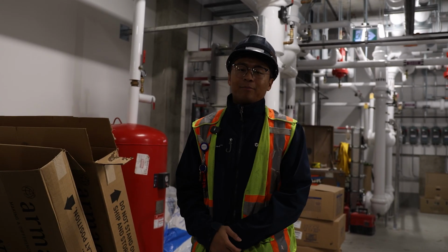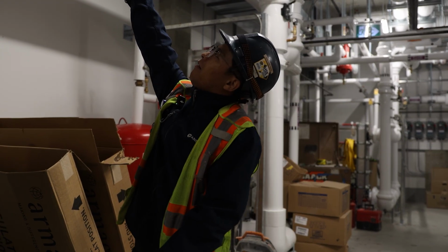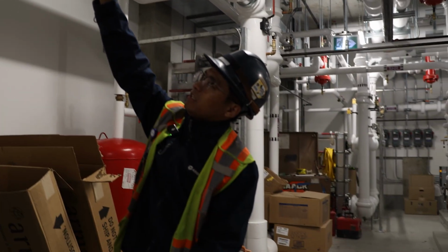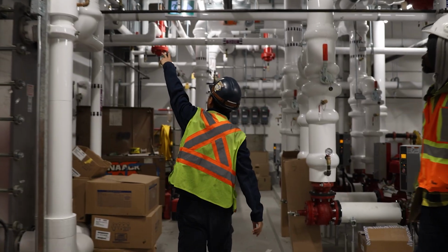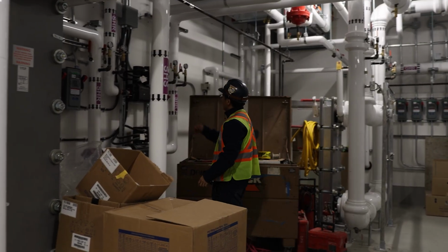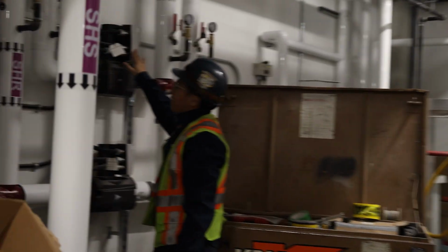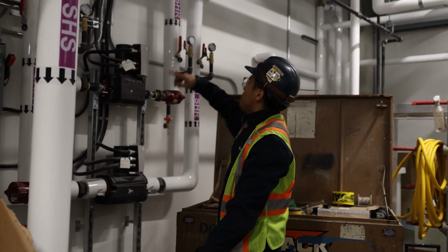Okay. Hello everyone, welcome to the solar section, domestic hot water solar. And those 2 are the pipes from the solar. One goes return to the solar, the other one is the supply from the solar. If we follow the pipe, it comes off pump 17. So pump 17 shall be running the whole time to do the recirculation for the solar system.